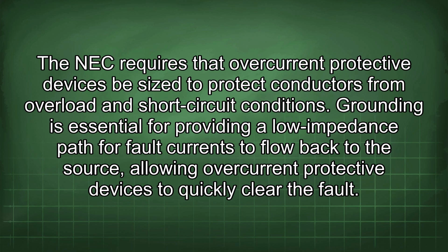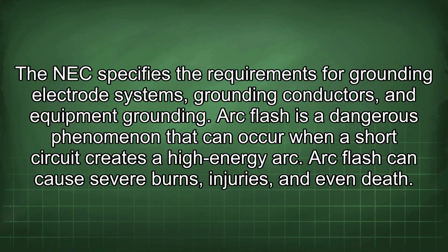Grounding is essential for providing a low-impedance path for fault currents to flow back to the source, allowing overcurrent protective devices to quickly clear the fault. The NEC specifies the requirements for grounding electrode systems, grounding conductors, and equipment grounding.